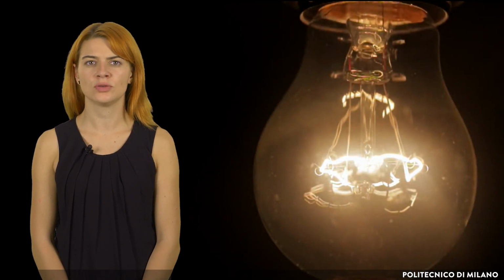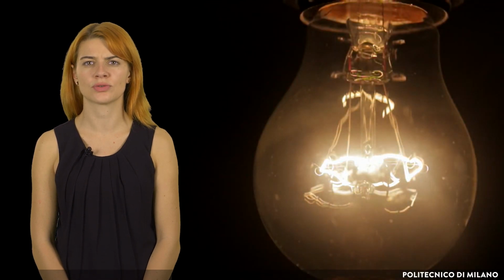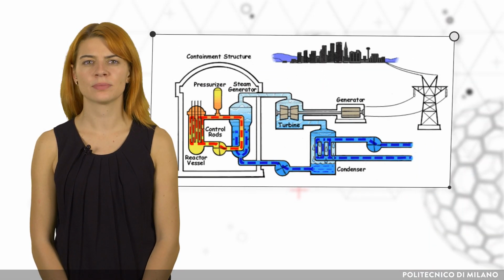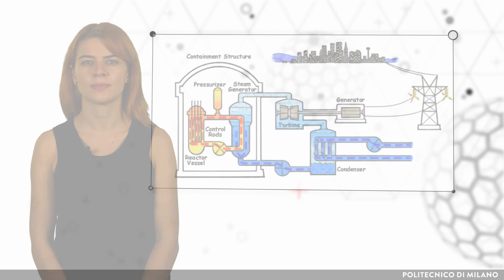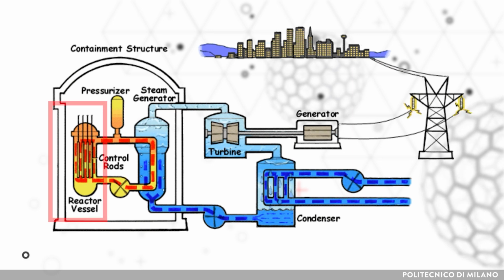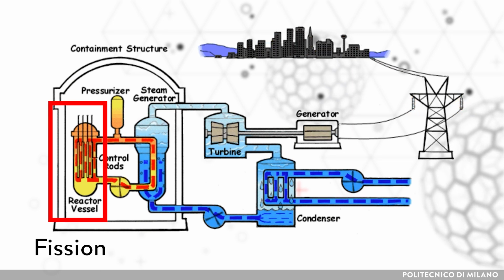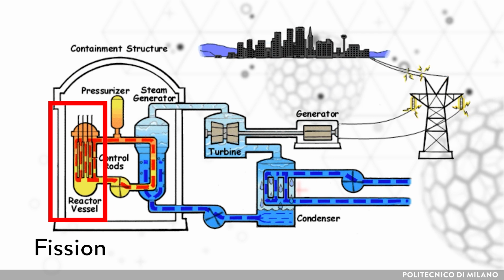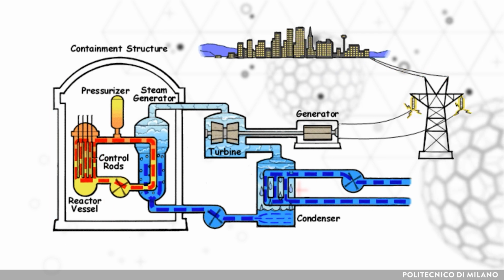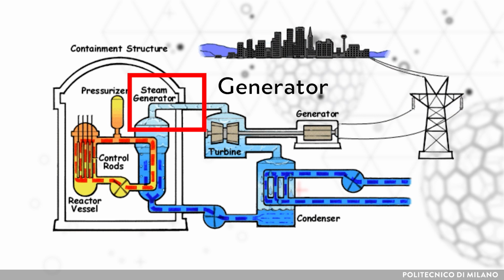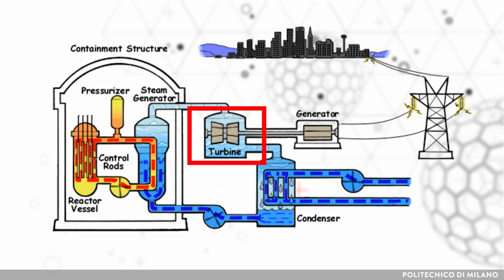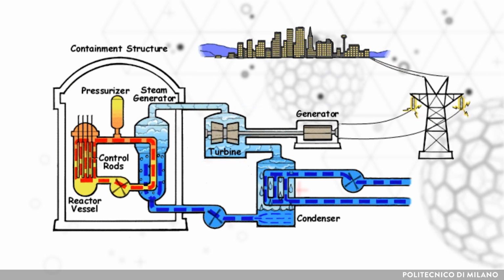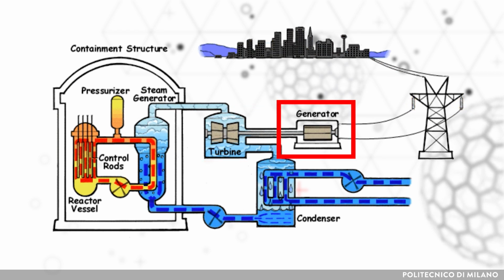Depending on their design, nuclear power plants differ in their degree of fuel enrichment, choice of coolant and neutron moderator. The general principle of power generation is the same for all types of nuclear power plants. In the reactor, a controlled nuclear chain reaction is maintained by neutron-induced fission of atomic nuclei. By energy transfer, the fission and decay products heat the coolant, which in turn drives a steam generator.